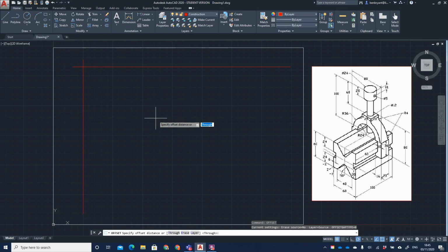First off, I'm going to arrange the top view of this V block, which is looking down, bird's eye view, consisting of 60 mm wide and 100 mm length. So I'm going to put in 60 millimeters and offset my first one, 60 mm. Remembering the command of escape and the spacebar to reload the previous command, I can type in my new dimension, and that gives me the physical length.